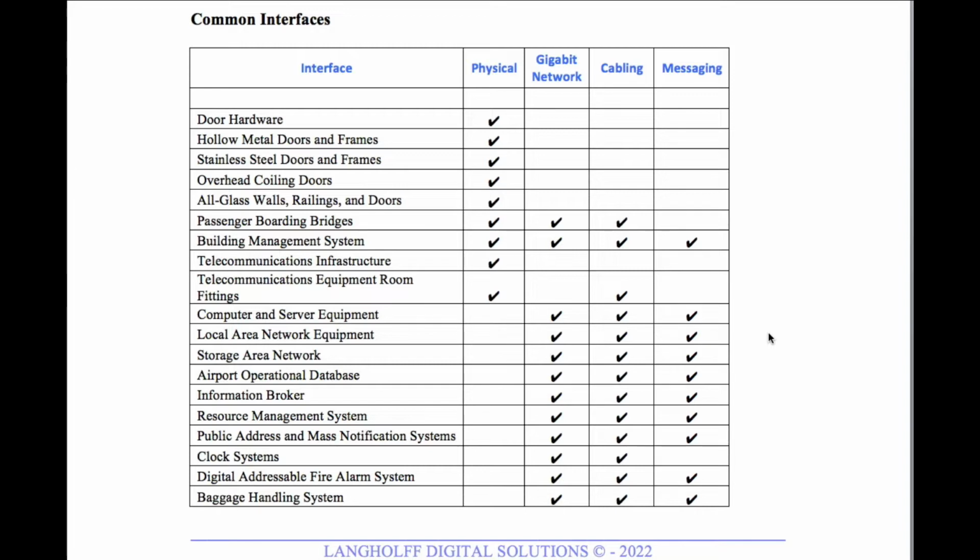That is not recommended because most of these types of doors have some form of fire rating. So it's much more beneficial, both in time and cost, to just specify that the door manufacturer must include the door hardware interface type, which you can define, and have them install it so that you maintain your fire rating on the door.